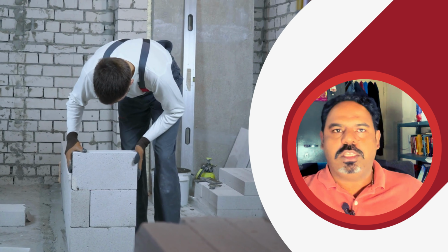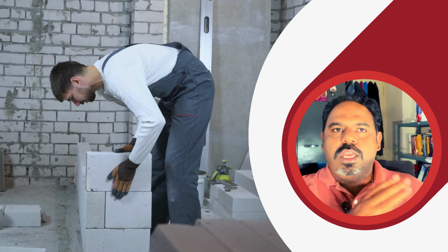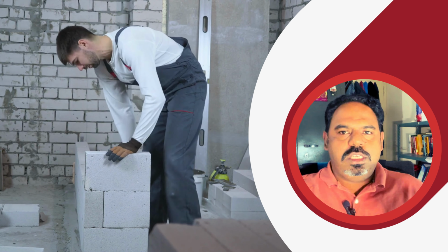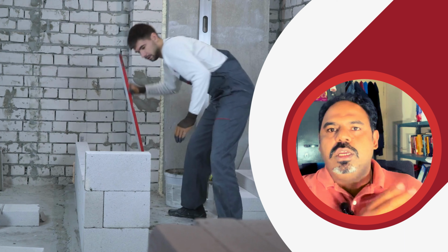For each hazard, we will mention worst case consequence risk. That is again, material, hazard is loose blocks and risk is fall of material. Machinery, hazard is nothing, so nothing risk. Men working at exposed height is the hazard and risk is fall from height. Procedure, hazard is poor scaffold, risk is collapse of scaffold. Environment, poor illumination is the hazard, so risk is trip and fall on the same level or fall from height.